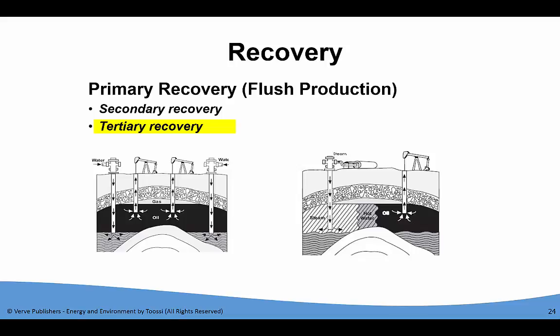So what do you do when you want to make honey flow from the honey jar? Well, the answer is that you either shake it very hard, or most likely you heat it. By heating it, you're cracking the heavy molecules into smaller molecules, and you cause it to flow easily. We would say we reduce the viscosity by heating. This is exactly what we do with the tertiary method. We are heating the oil well.